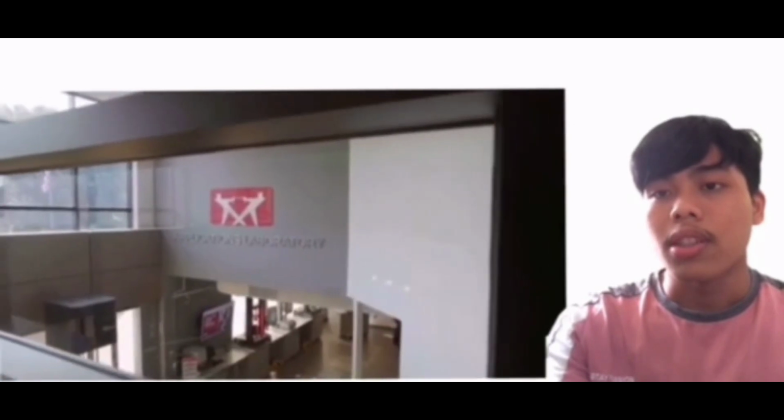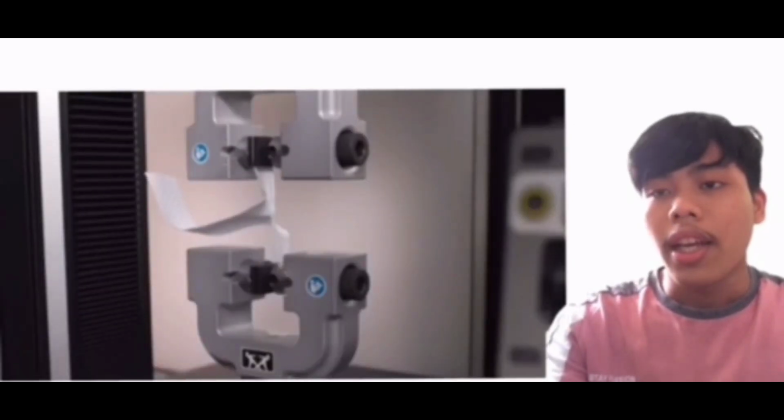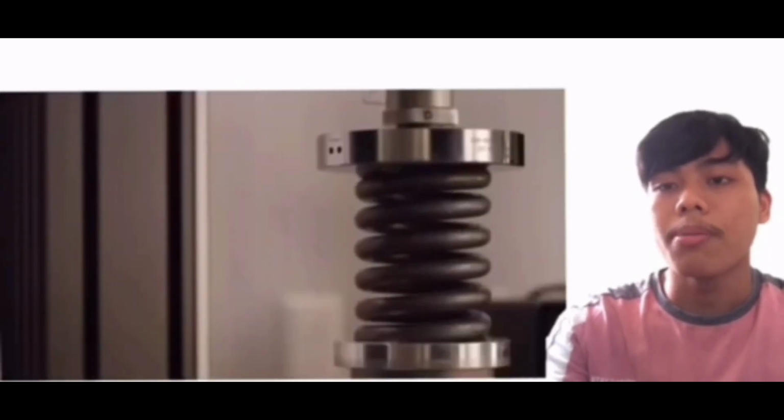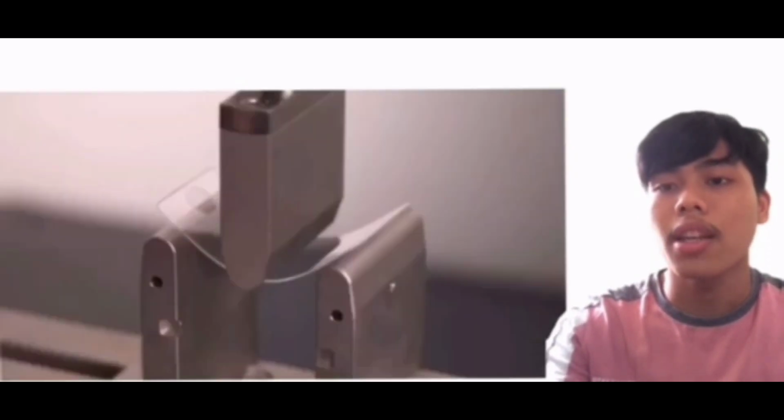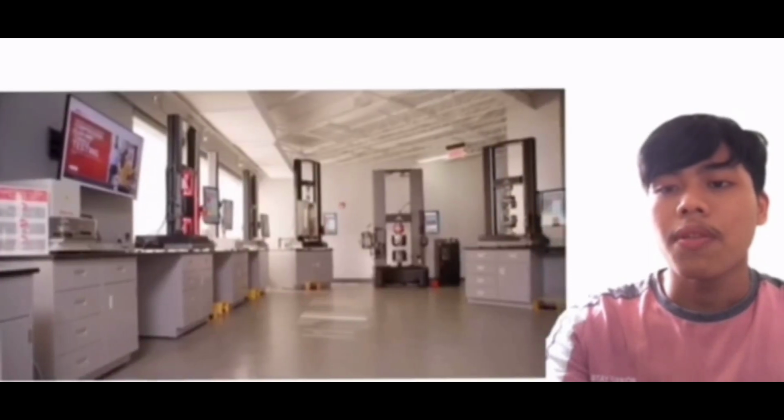The conclusion. The tensile test of steel and nylon had consistent and accurate results. It was shown that the strength and stiffness properties of steel were much higher than those of nylon. The experimental results for the material properties tests of the two specimens were close to the established values.